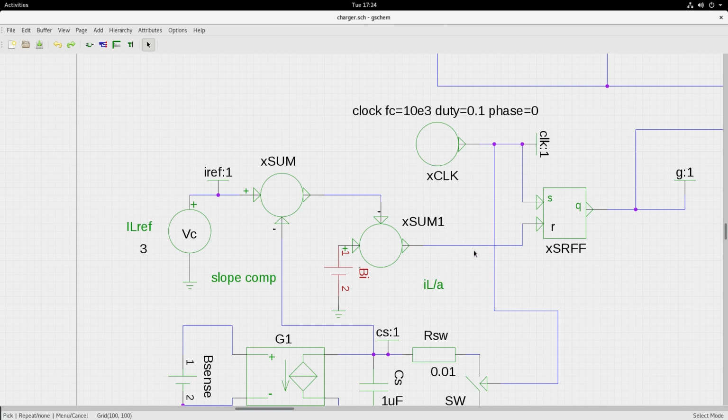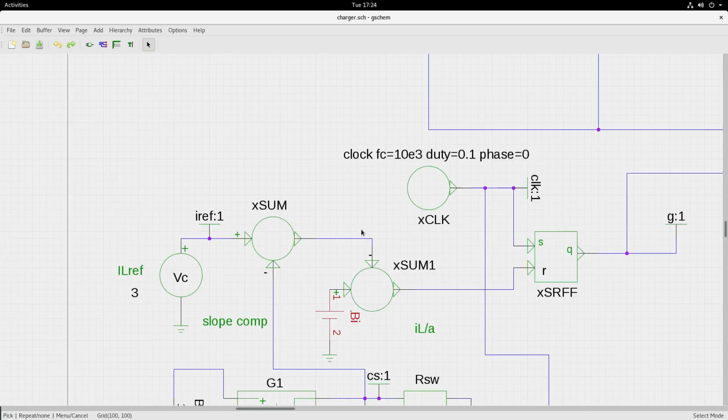We had put a comparator here with a minus and plus with an inversion, and this comparator block I have removed and then did a sign change here itself, minus and plus. The inversion caused by the comparator is brought forward and I have inverted the sign here because there is a Schmitt comparator at the input to the SR latch itself. So that is the only change.